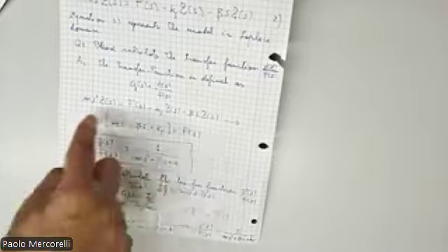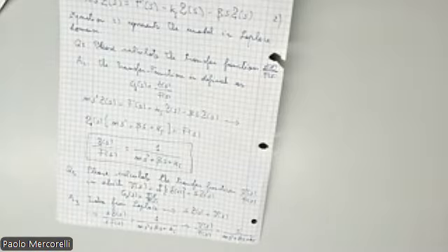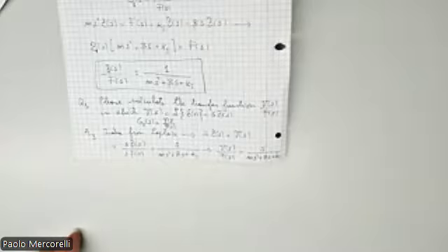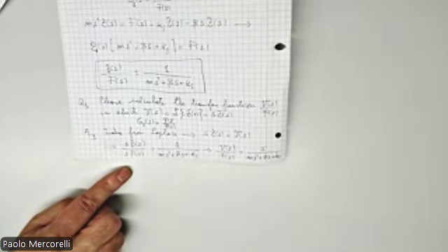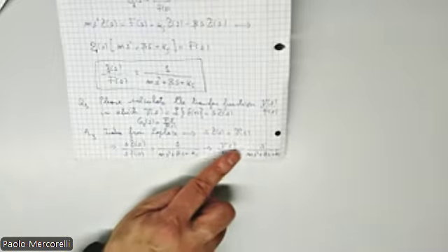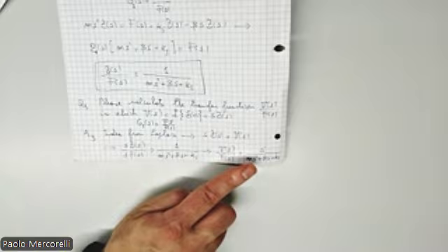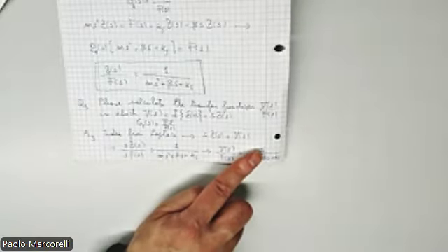But somehow we can see that, of course, we lose the physical meaning here because we are in an imaginary domain, the S domain. But everything was, until now, calculated formally, basically using some theorems, just algebraic considerations. And then you remember, in the same way we calculated the transfer function between velocity and force, we can see that the denominator does not change. Very important. I told you last time, the same denominator, changed just the numerator.